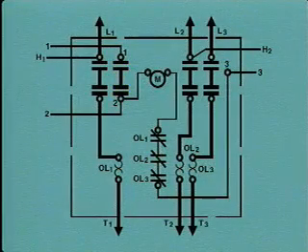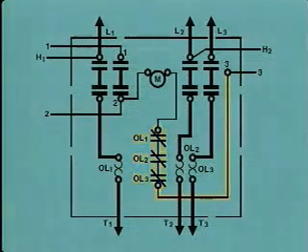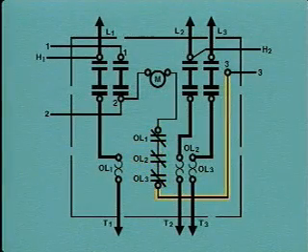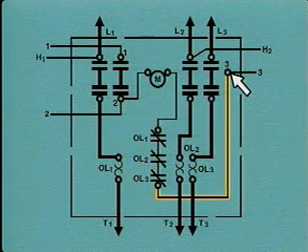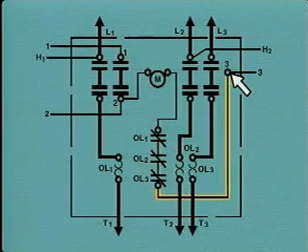The other side of the M coil is connected to the 3 overload contacts. From the overload contacts, a wire connects the control circuit to connection point 3. Connection point 3 indicates where the control circuit is connected through fuse F2 to the X2 side of the transformer.